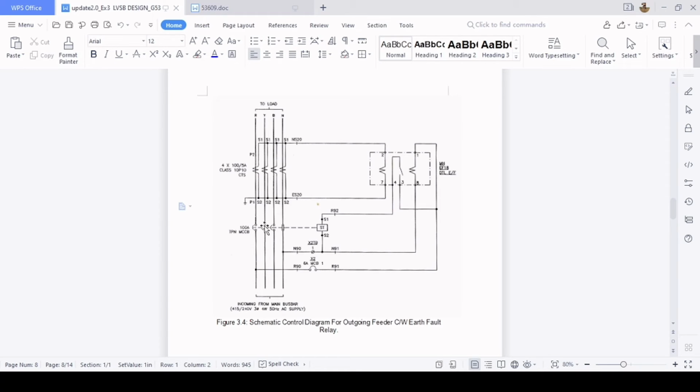The circuit breaker will then connect to the ST, that is the shunt trip coil. After that, it will connect to the coil or contact. It has two types, that is normally open or normally closed. This figure is in open condition. When it is in open condition, the coil is closed and it will give a signal to the circuit breaker to open, and then the ACB will open.